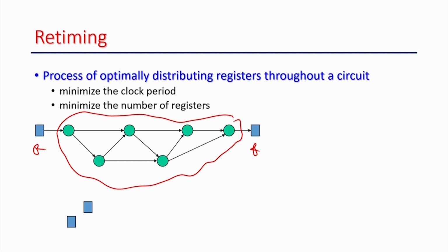Okay. So, what is happening here, you can see that the maximum length here is 1, 2, 3, 4, so maximum 1, 2, 3, 4, 5. So, the maximum combinational length is this, right. This is 5, so the number of gates in a path is 5. Whatever delay you are going to get is the summation of the delays for this combinational unit. All the AND gates, OR gates, have some delay associated with them. They need some processing time, that is the combinational delay of that particular node. So, the maximum clock period will be determined by these 5 units of gate delay, right.